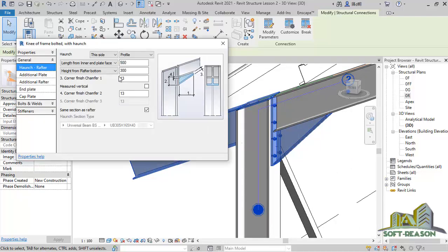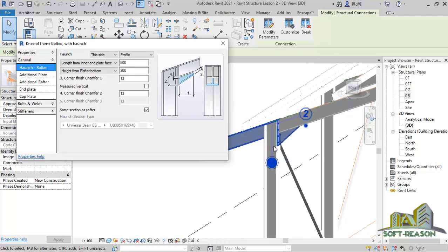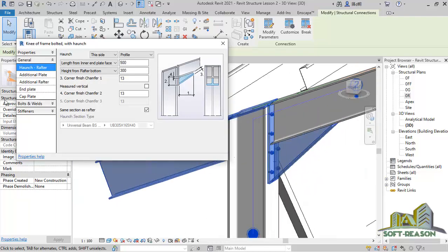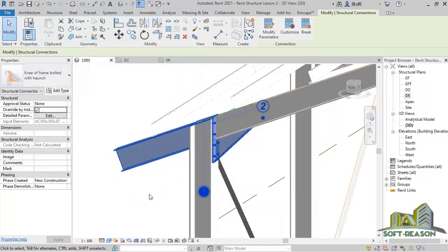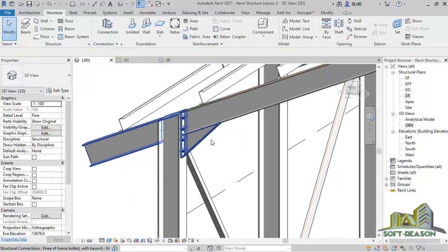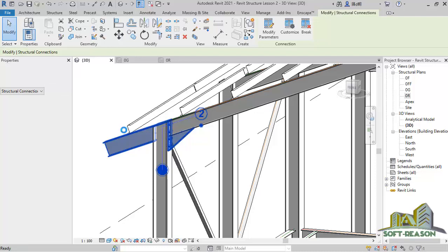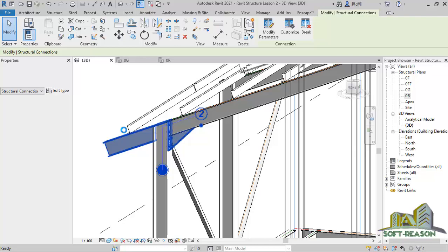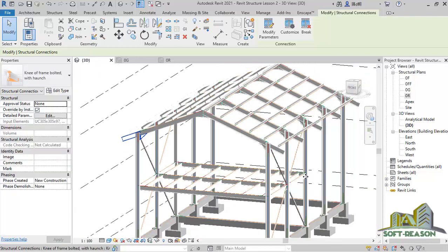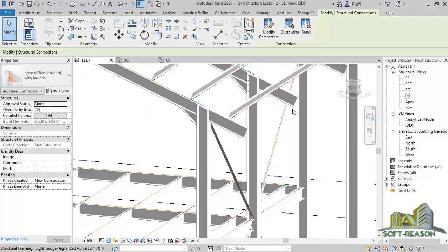If you check very well now, I changed this to 500. It has actually affected these arch braces. Okay, so this is okay. We'll be going by this. I will just have to close this one. You can also do some other changes. I want to propagate this to other parts by right clicking it. Click on propagate connections to propagate it to other parts. We just give it a minute. Alright, you will notice that is done, even including this side.